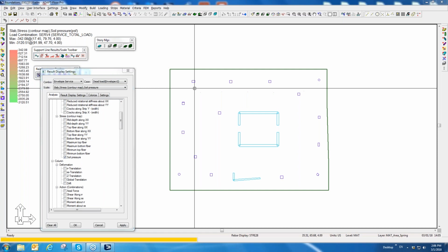And you would either have to increase the concrete strength, you might have to increase the concrete depth so that you drive up the allowable capacity of the concrete, or if you used a pile that had less bearing capacity, which may not be the answer, but I'm just throwing out ideas. If you used a pile that had less bearing capacity, then you would limit the amount of stress that could be imposed on the slab based on that pile size.